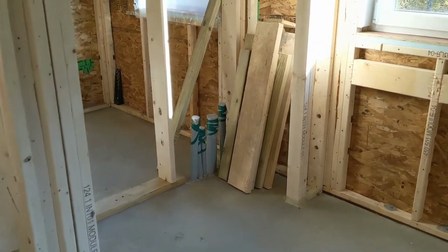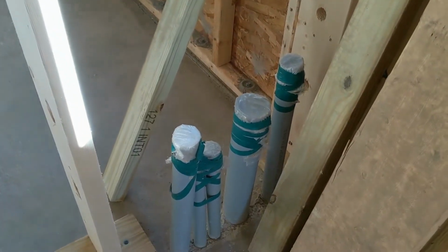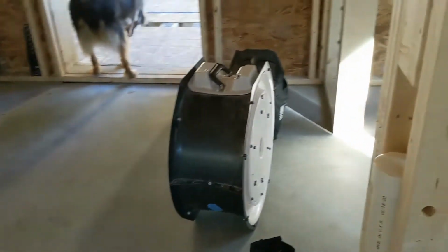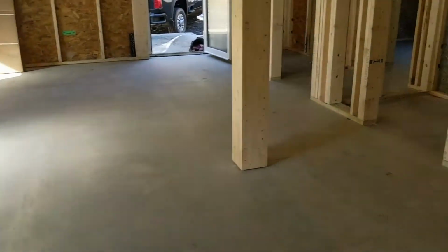So in order to do a blower door test, you want to seal all the penetrations through the shell and the slab. So any pipes, any conduits, any knockouts, any chases, any vents. Fortunately, these have mostly been sealed. I'll double check. Gonna have to cover up things like this conduit, but there's caps on everything. The caps appear to be tight.